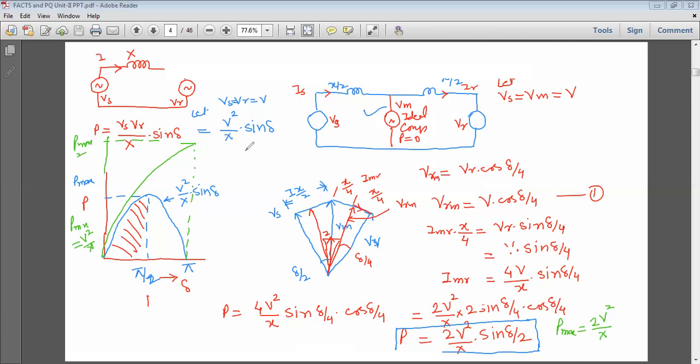Now, as we know in the conservative criteria, which we have already done in power system stability, we never operate our system at the calculated value, but much smaller than the calculated value. So even if you operate here, the power handling capacity is quite good compared to without compensation.